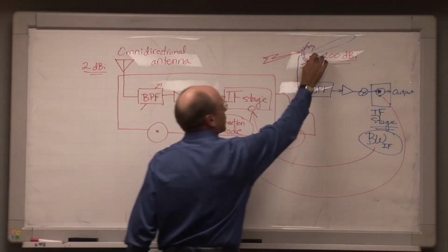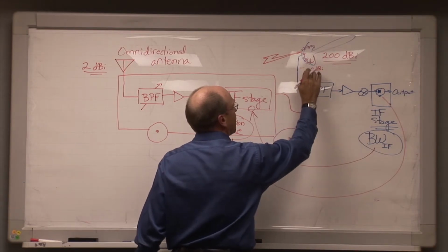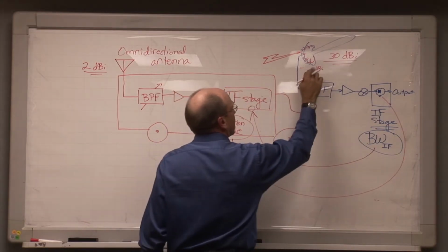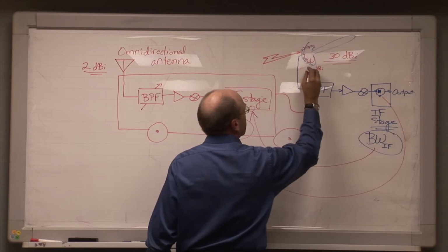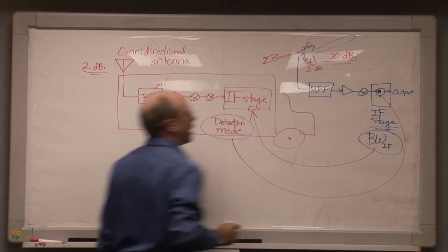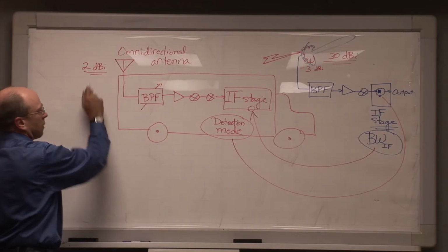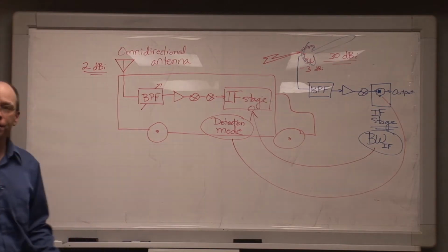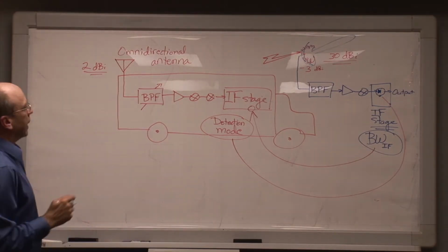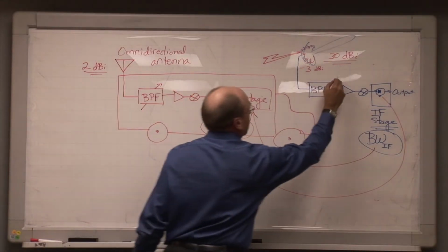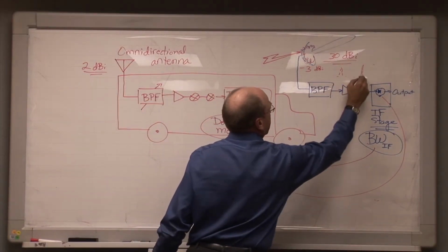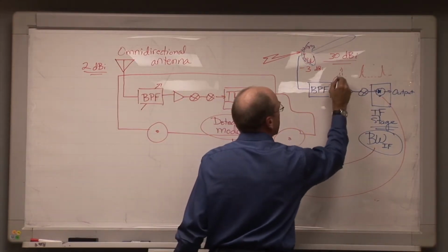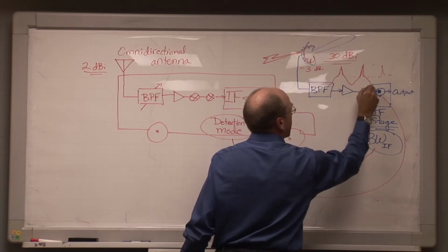Now, they might be running a lower gain antenna, so their side lobes might not be so low. Maybe they're only running say a 30 dBi gain antenna, in which case maybe this is, and again I'll pick a number here, minus 3 dBi. Well, again, if we're running 2 dBi gain on our omni, we've still got 5 dB more gain on our antenna in whatever direction the interference may be occurring than they've got. So we'll see the interference better than they will, we hope. In fact, where they might see the interference kind of coming in and then dropping out and then coming in and dropping out as time goes on, we might get to see the interference a lot more of the time because we'll be seeing the interference all the way down into here and up and down and up, okay?